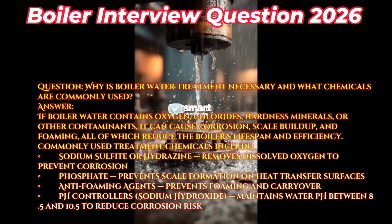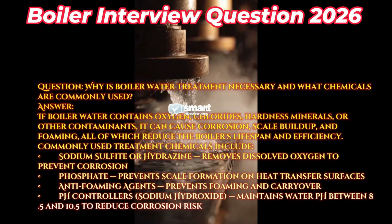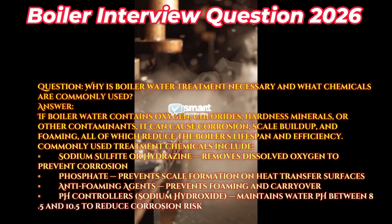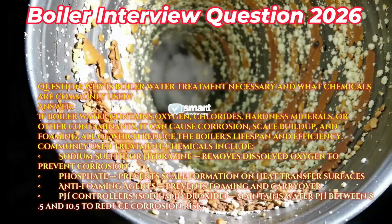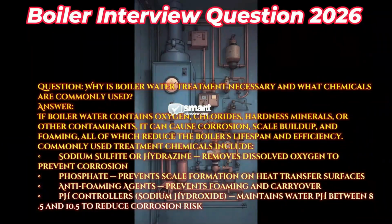Commonly used treatment chemicals include sodium sulfite or hydrazine, which remove dissolved oxygen to prevent corrosion. Phosphate prevents scale formation on heat transfer surfaces. Anti-foaming agents prevent foaming and carryover. pH controllers, such as sodium hydroxide, maintain water pH between 8.5 and 10.5 to reduce corrosion risk.